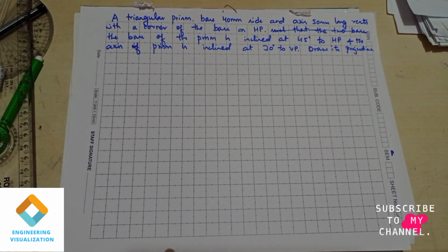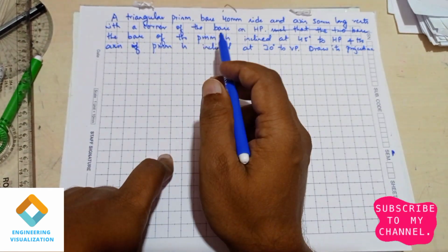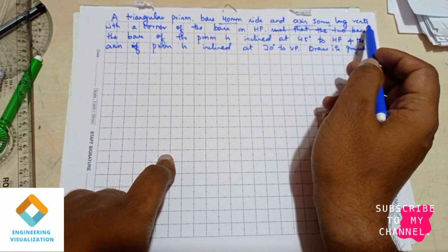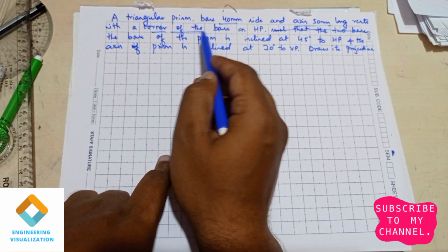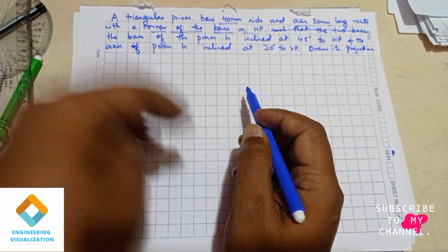Today we are going to see the next type of problem. It is a triangular prism. So what is given here? We are given a base side of 40 mm, axis length 50 mm, resting with a corner of the base on HP. So we should be considering the corner on the right hand side.